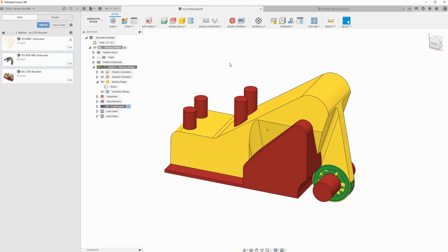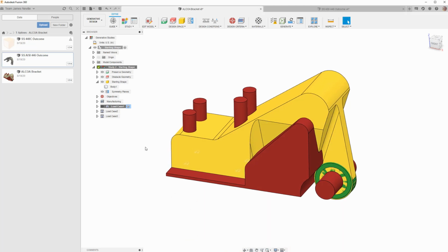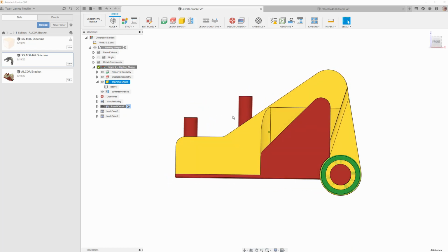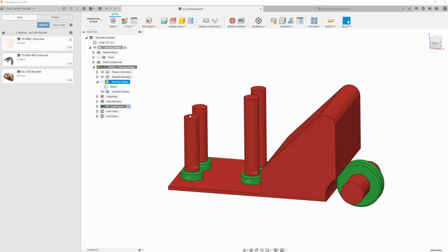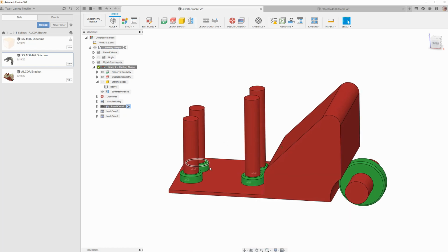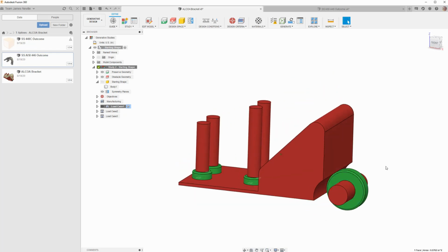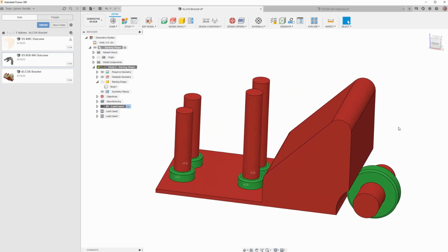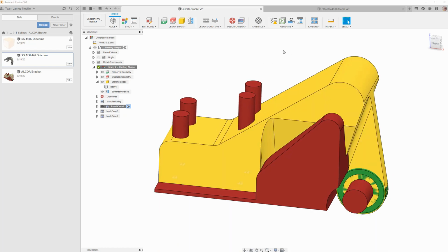All right, so this is the Alcoa bracket example. Again, it's located in those generative design example files in everyone's installation. It does have a starting shape. You can see that, the big yellow starting shape. We just chatted about these. This model actually will not run without a starting shape, because there's no line of sight. There's no direct way for it to connect these preserves over here to this preserve here. So without a starting shape, this one won't actually run, which is interesting. So you must run this with a starting shape. But this is the model that we're going to use for the T-spline workflow.